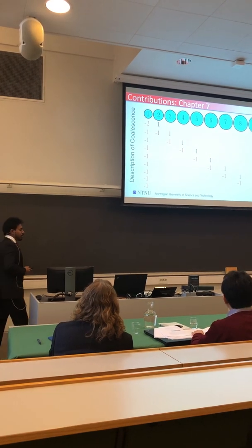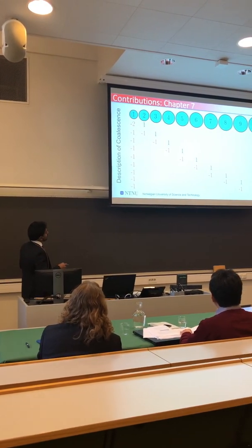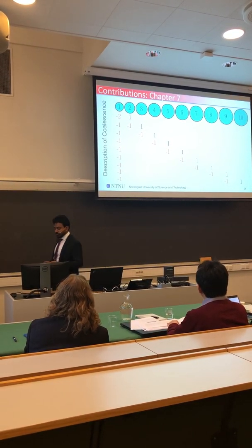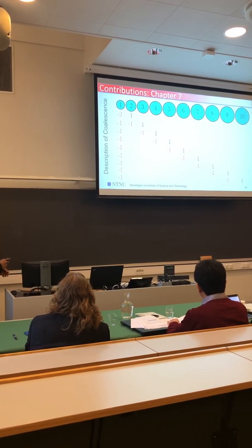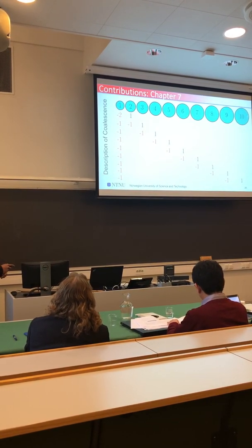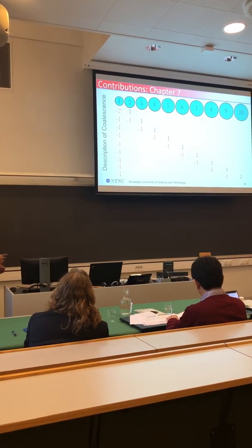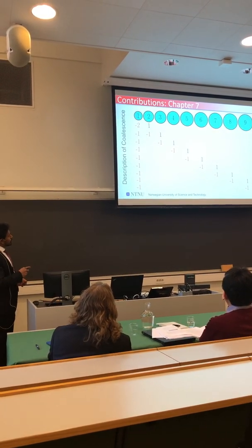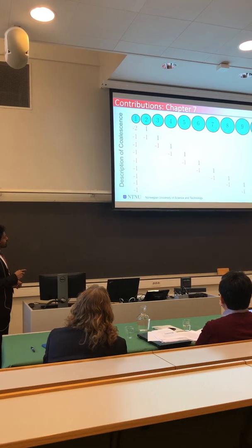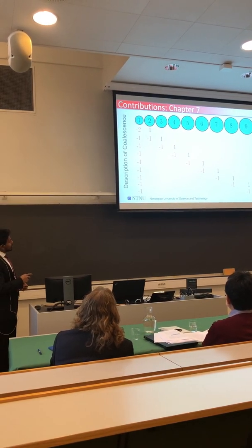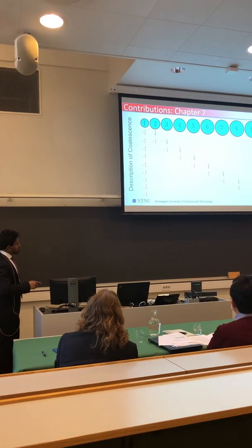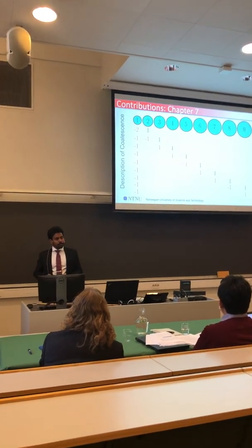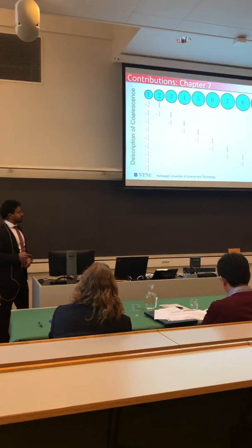And number 1 is 150 micron, and number 10 would be cube root of 10 times 150 micron, and cube root of 10 is roughly in the range of 2 point something. So we covered a range from 150 to 320 micron, and we described this using chemical reaction kinetics, that 2 of these combine to become 1 of these. So the negative ones are denoted in red and the positive ones. This is the starting of the stoichiometry matrix, and of course it doesn't end here, there are many more equations. In total there are 25 equations to describe these 10 droplet classes.